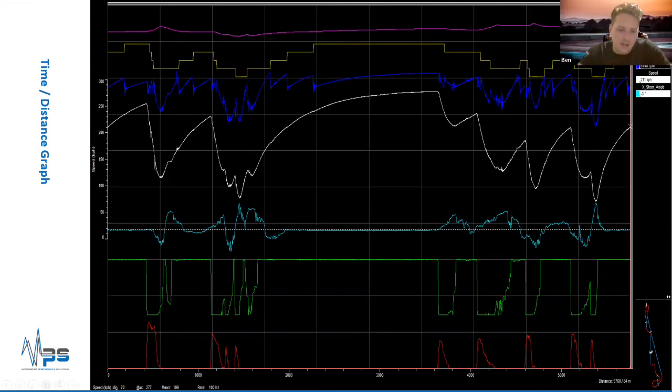The reason we do that is because, generally speaking, there are exceptions here, but generally speaking, turn 1 at Paul Ricard will always occur at, I don't know, 540 meters into the lap. So if you want to analyze yourself to yourself, or analyze yourself against another driver in your car, you've got a constant in your data, which is turn 1, give or take, always occurs at the same point. So if one driver is braking too early in comparison to the other, or one's too late to turn in, you have this distance measurement that you can reference on track.